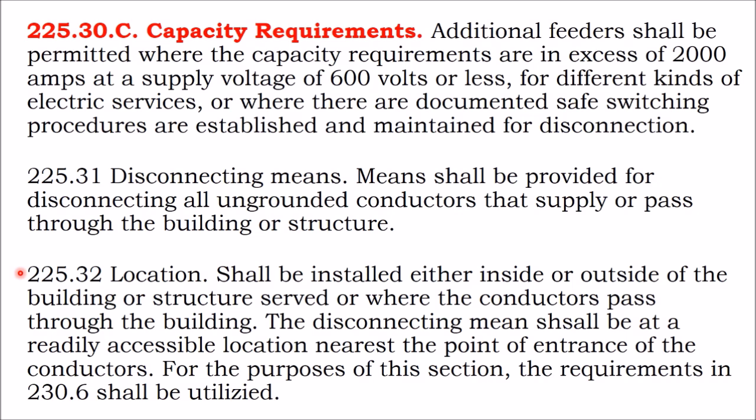So sometimes you get an external disconnect on the inverter that's built into a separate housing compartment than the rest of the inverter system. So you're not unwiring the entire inverter and the entire solar array to service inside the inverter. So that's a pretty good feature. So you would want the disconnecting means to be next to the inverter so you could just go up to the inverter, flip the switch, and service it. But really what the utility wants is the switch to be outside the building, because what they're concerned about is being able to easily turn the system off if there's an emergency.